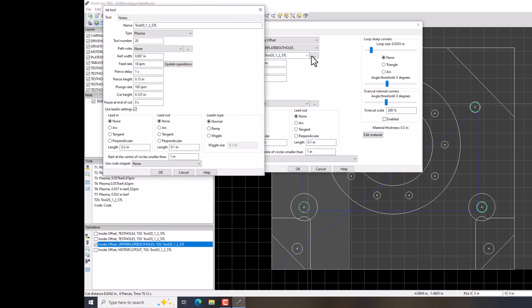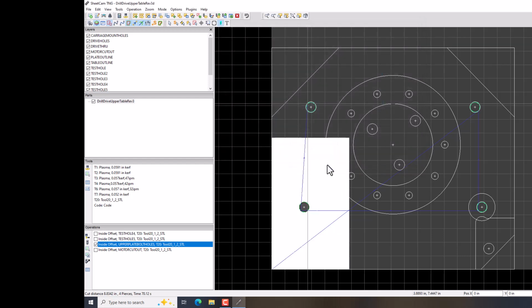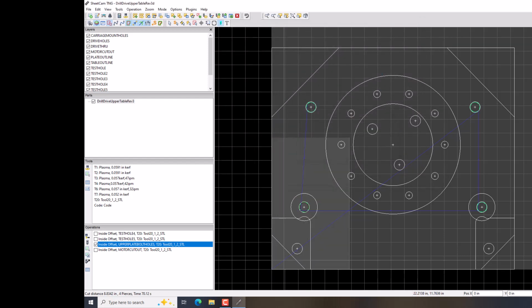And real quick, what I'm showing you here is where the part is actually imported into a separate piece of software that generates tool paths based on basically what sort of machining you're doing. In this case, plasma cutting. And then what I'm doing here is just making sure that the parameters are correct for the material as well as the torch that I'm using, in order to make the cut successful.